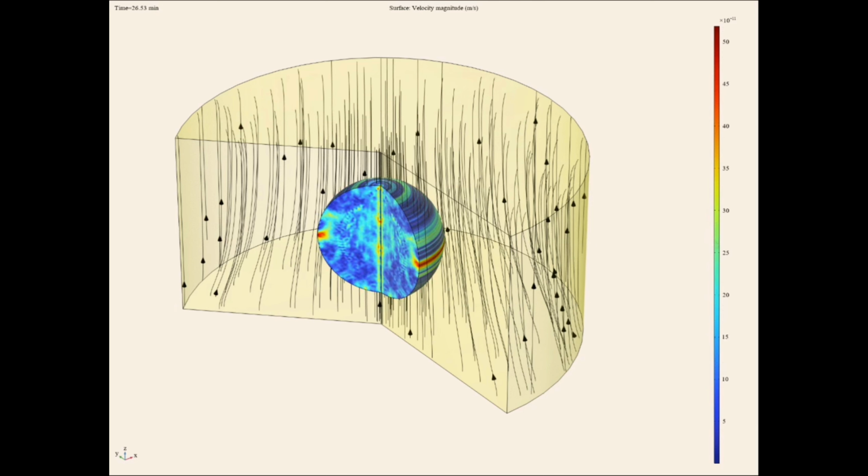However, as the pellet becomes more porous, the unreacted shrinking core model, which assumes a sharp reaction front, can no longer accurately represent the process. Therefore, in our model, we use porosity and tortuosity parameters to account for the pellet's structure. As you can see, the gas diffuses in, and after the hematite reaction, the process no longer progresses in layers.